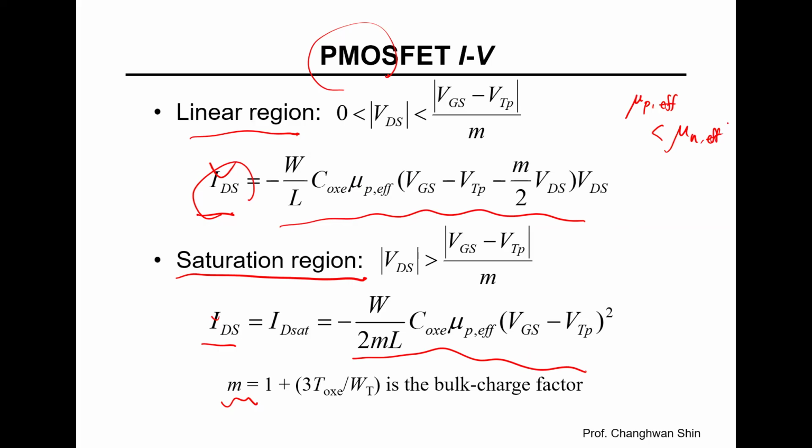This means that PMOS transistors must be wider than the NMOS transistor to achieve the same current drive capability in digital circuits, which is like needing a wider lane for slower moving traffic to maintain the same flow rate on the road.